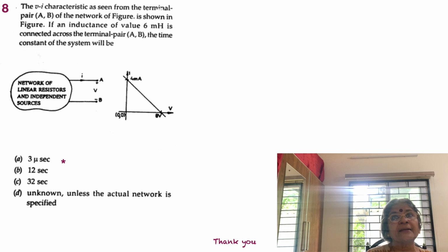So this is a practical thing that we do. We try to discharge the energy. We are having an inductor here, and we are trying to see what will be the time that is involved for discharging the energy. So we have 6 millihenry, L, and we also have R as 8 by 4, 2 kilo ohms.